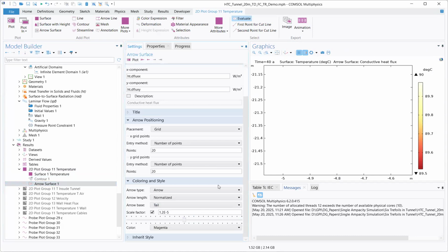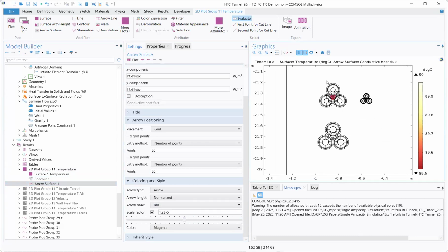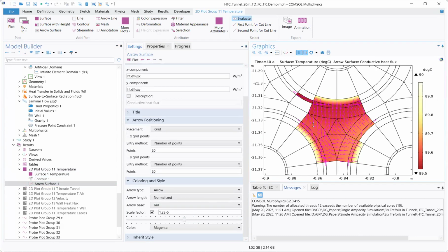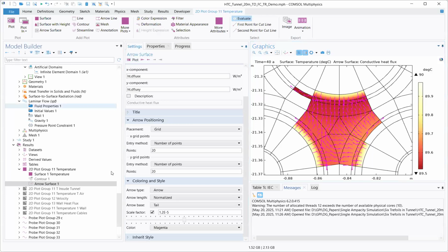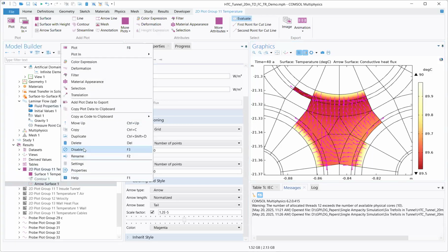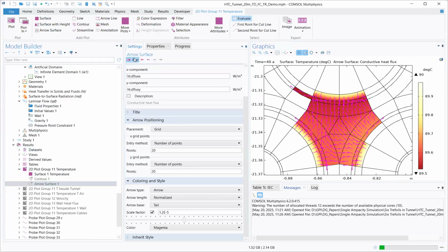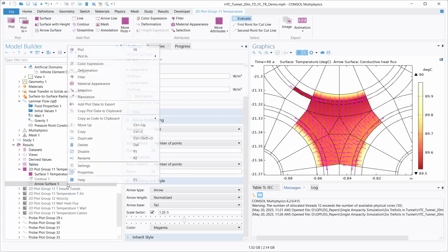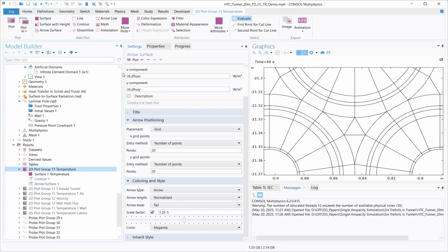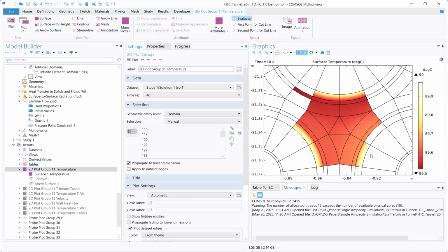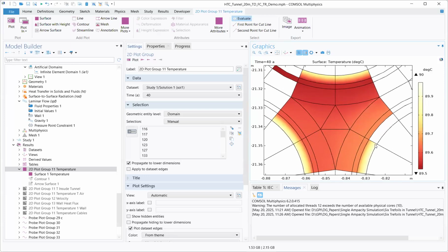So he is not simulating the deformation due to heat. Deformation due to heat is not being simulated, no. But David, you can see here, the temperature is about the same everywhere. So nothing here moves, nothing radiates. You can eliminate it. But if you eliminate it and don't model it correctly, it will not converge.